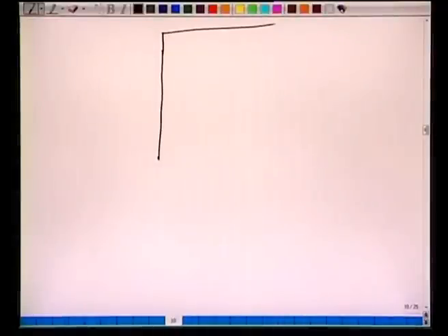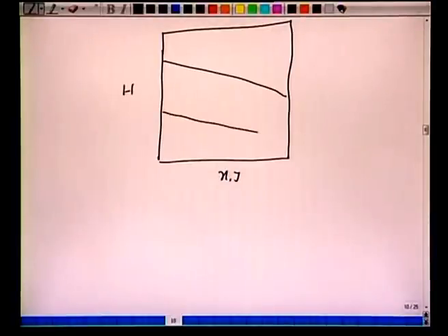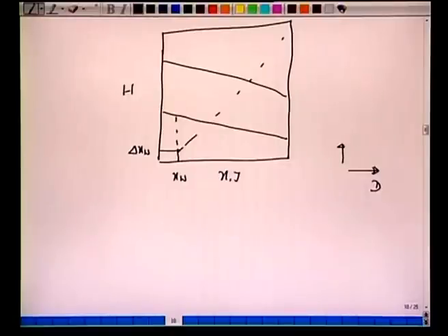So we redraw this HXY diagram. Now we focus on this stripping section. All right, so this is XW, and let's say this is your del XW, which you have obtained by connecting the feed, etc. Now the bottom product, when we withdraw this D, the liquid which goes out from this is in equilibrium with the vapor reflux which goes to the bottom plate of this column here.